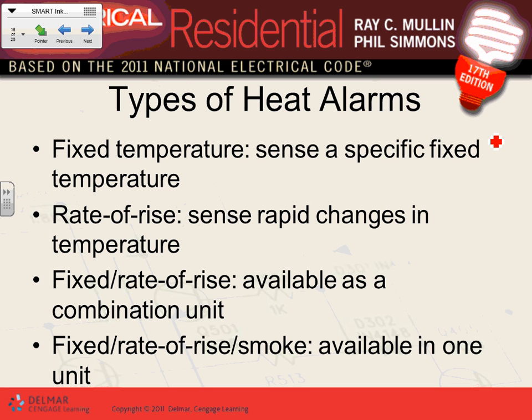It's not required. Why? Because if you put a smoke detector in the kitchen, what happens? Nuisance tripping. You don't want nuisance tripping. So a heat detector would be a good application in a kitchen. A garage could be a good application for a heat detector too. Okay, so the technologies that they have. Technology number one, guys, is fixed temperature. When the temperature hits 100 or 110, it goes into alarm. That's fixed temperature. They fix a certain value.